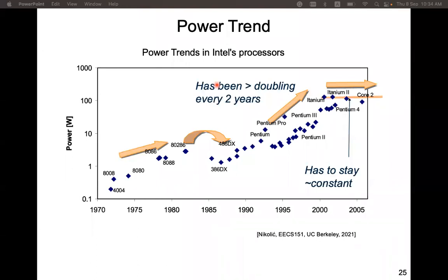Over the years, the supply voltage has been reduced, but clock frequency increased. But supply voltage has little room for further reduction. It is now around 1 volt. If we increase clock frequency, then this will certainly increase the dynamic power. Of these two components, the second part dominates. Dynamic power is the useful power, the power used to perform some useful task. Leakage is waste power.